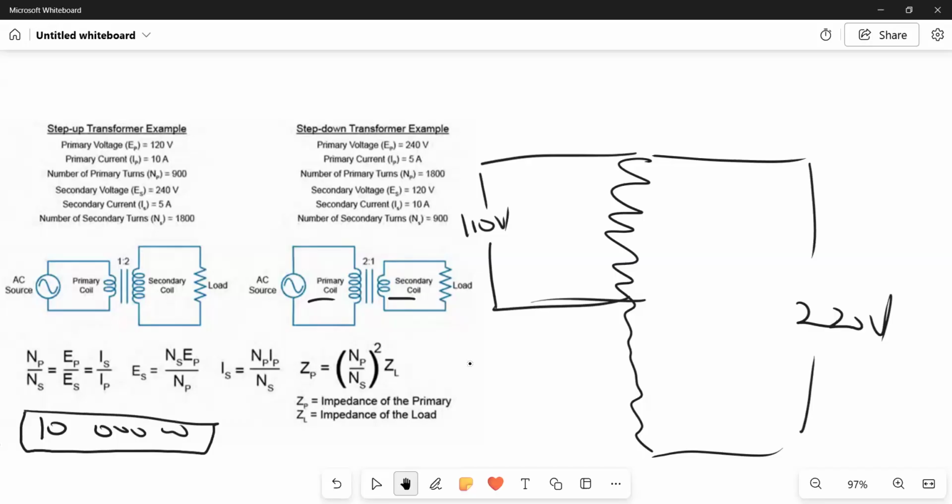And when I actually wired it up, I'll tell you what happened. I bought my fridge, and when the guy plugged in the thing, no, before he plugged in, he tested my point, and he said your neutral is live. I said, what? And he said, yes. You know why? You think that you have an isolation transformer, but no. The Chinese transformer is one big coil, and they just put a center tap.